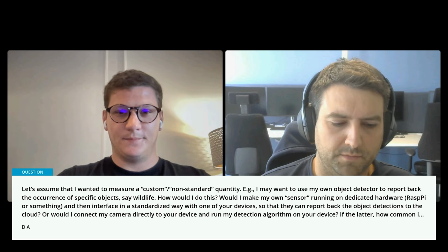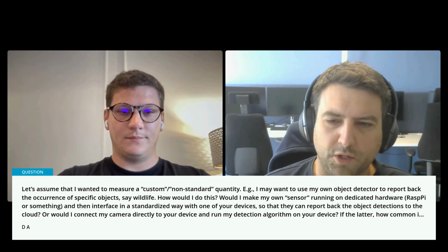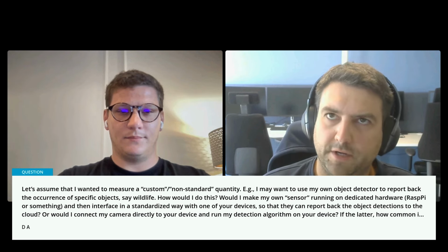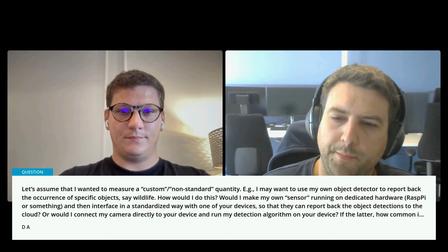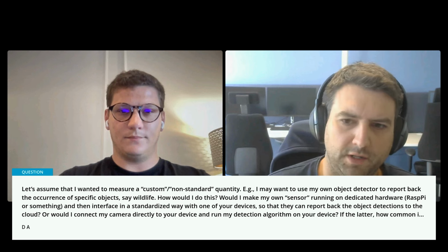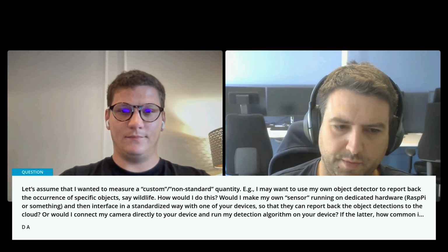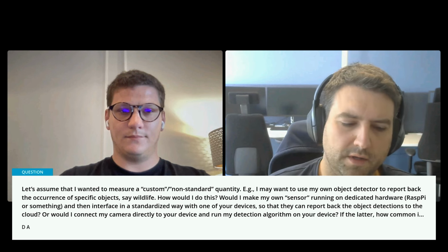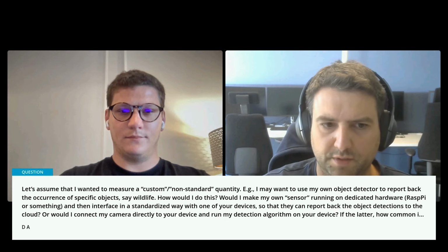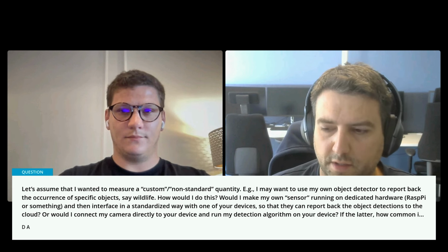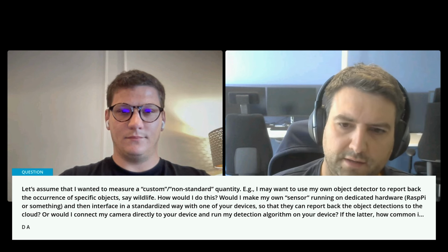Yeah, exactly. Obviously we at Nordic, as well as our partners at Golioth, are well aware that programming in Zephyr, or based on Zephyr, can be a bit strange depending on your background. If you're an embedded Linux engineer, this will be great for you because it reuses a lot of concepts from Yocto Linux, device tree and the Kconfig system. If you're coming from a more bare metal or low level type of environment, you'll see things that need to be learned because there's more abstraction and more infrastructure. But the beauty of that is that long term, you'll reap the benefits.